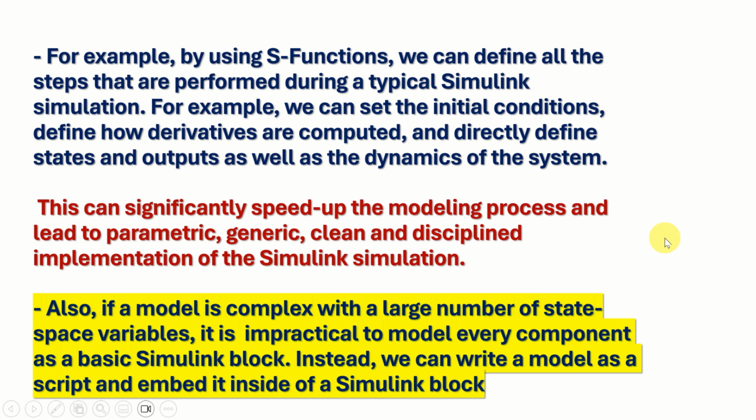For example, by using S-functions, we can define all the steps that are performed during a typical Simulink simulation. For example, we can set the initial conditions, define how derivatives are computed, and directly define states and outputs as well as the dynamics of the system, and everything is done inside of a script. This can significantly speed up the modeling process and lead to parametric, generic, clean and disciplined implementation of the Simulink